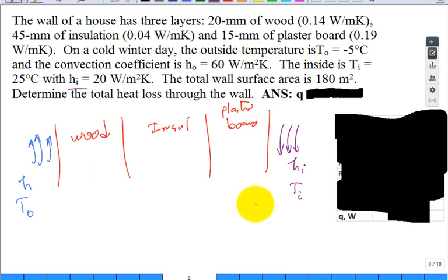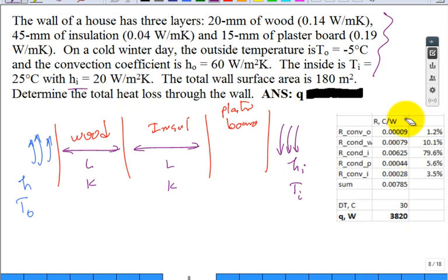I think I outlined how to solve this problem enough. If you chase these numbers down, they give you the thicknesses and the thermal conductivities, the L's and the K's. You can do the bookkeeping and solve this problem. Here is an Excel sheet. Because of accountants, bookkeeping, we don't want to make errors. Sometimes things are tedious. If it's on homework, great, use Excel to check your work, but also develop the skills such that during an exam when you can't use Excel, you can do it correctly as well.